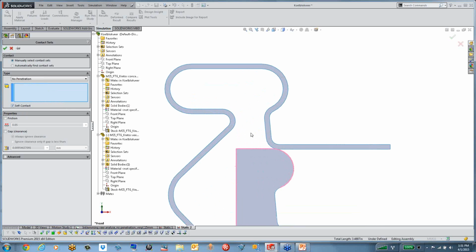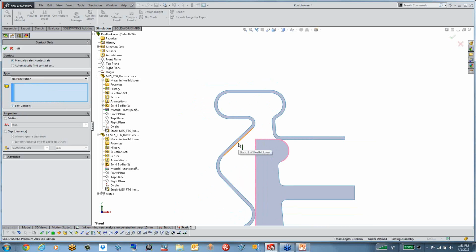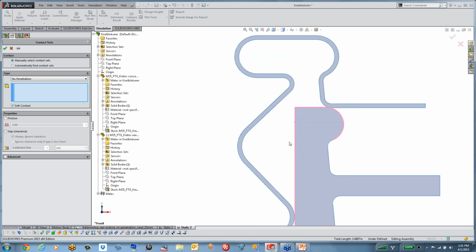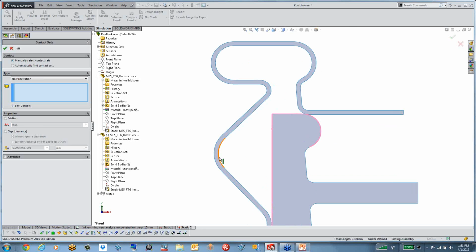So in this example, as you're pushing this and this top piece is bending, this curved surface over here might get squeezed so much that this endpoint might end up touching this endpoint. So what I can do here is say this curved edge is probably going to self-contact. I don't know for sure, but if you suspect that scenario might happen, you can select this type of contact. The workflow does not really change. All you do is check this box called self-contact, and there you go.